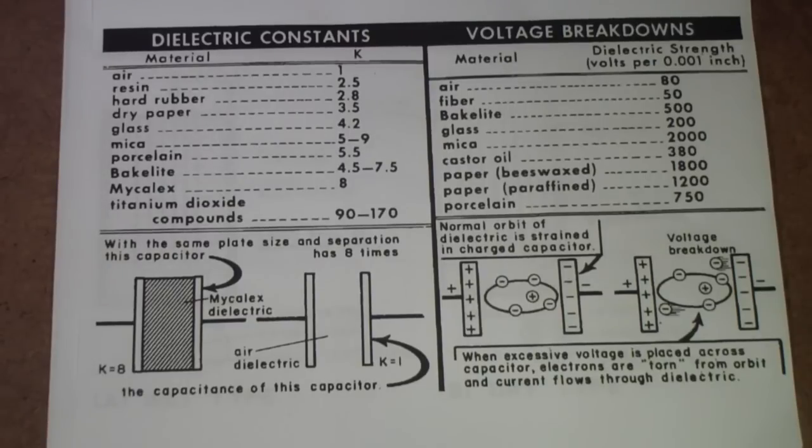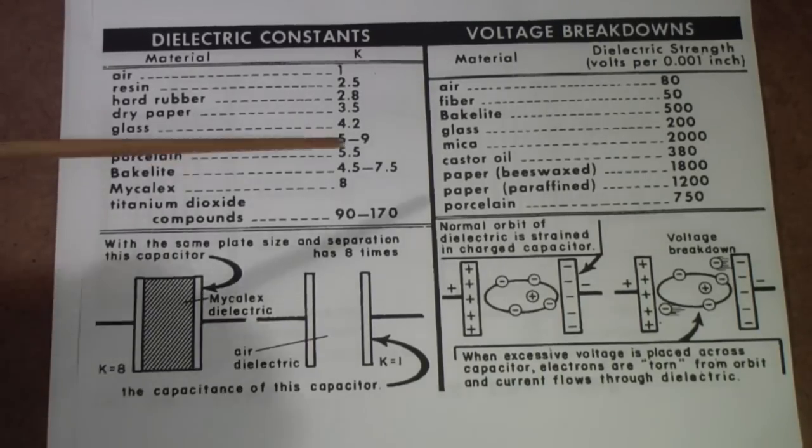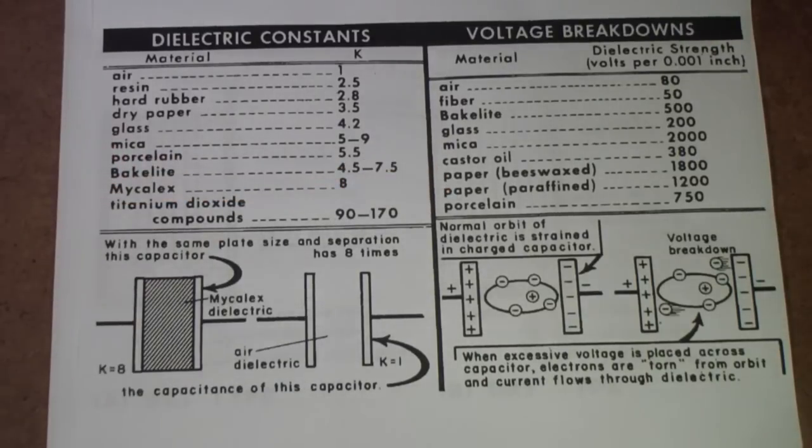However, in these old radios, in general, it's best, because the paper breaks down, to replace all the old paper capacitors. Once again, I said we'll get to that when we get there, but for right now, I hope this has given you an overview of the wide variety of things in an old radio that are called capacitors.